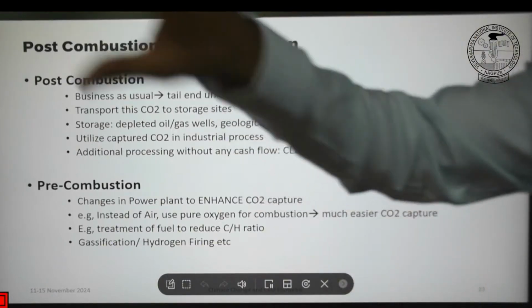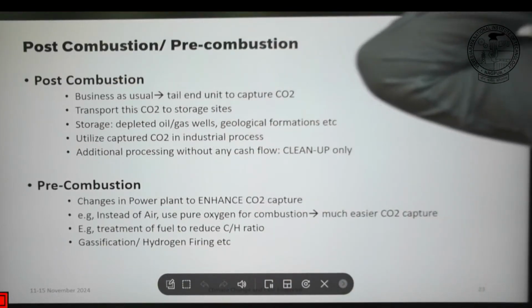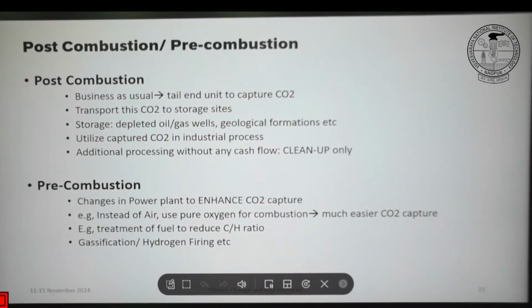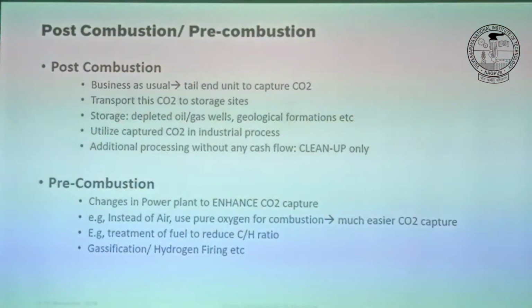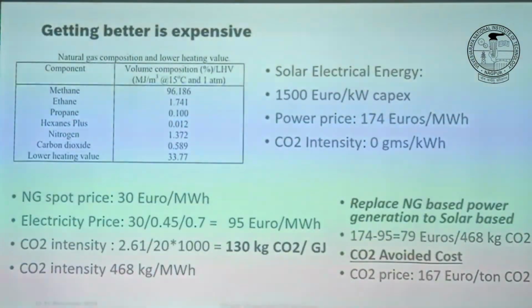So pre-combustion, post-combustion, that's the basic difference. In post-combustion you let your business run as usual, like in a power plant, and whatever flue gas you normally send to stack, you take it and put a tail end solution. And pre-combustion is before combusting your fuel, you do some treatment, you do some tricks so that you have less CO2. So that's also very common terms.